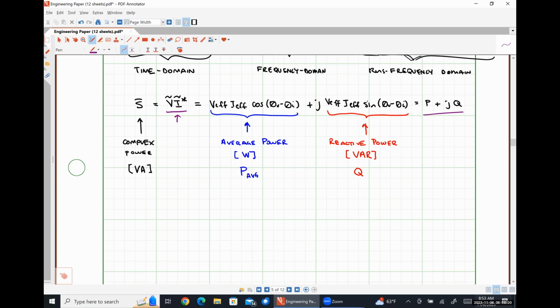So you may ask yourself, well, what is it really doing if it's just getting sent back and forth between the utility and the user? It's temporary energy storage for the grid. Without significant reactive power in our grid, every time multiple people turned on their ovens at the same time or something like that, we would have a blackout, right? So imagine, I think this happened the last time, it was a big soccer tournament, I think, in England.